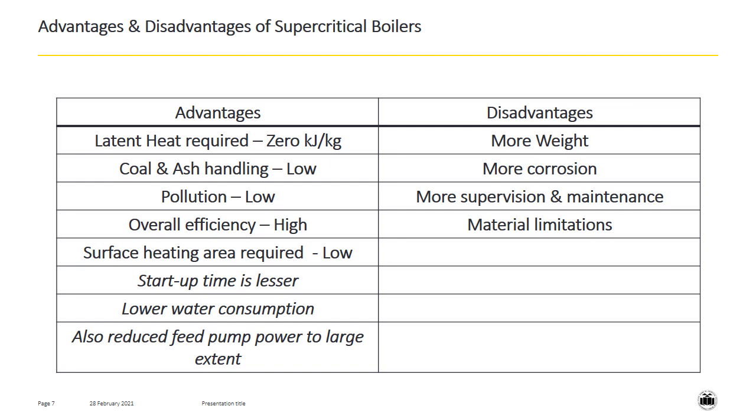Startup time of these boilers is less than subcritical boilers. They have lower water consumption, and there is also a great reduction in feed pump power requirement, as the feed pump uses a lot of power from the power generated by the power plant.